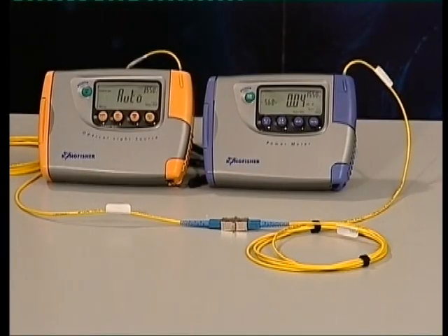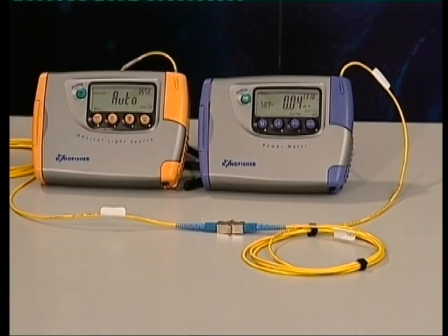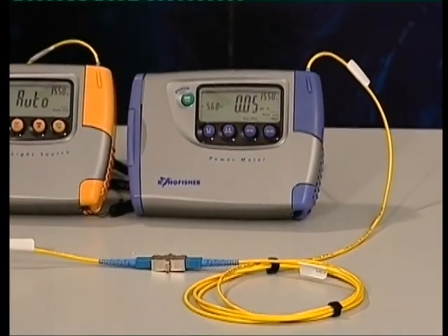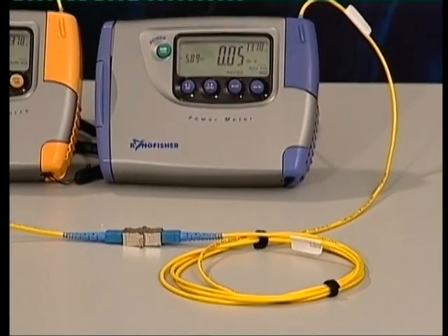We will now discuss connectors and test leads. Test lead fibre type and connector type should both match the system under test. Practical testing is performed with a low-loss test lead attached to the instrument for the duration of the test. These leads form part of the test apparatus.